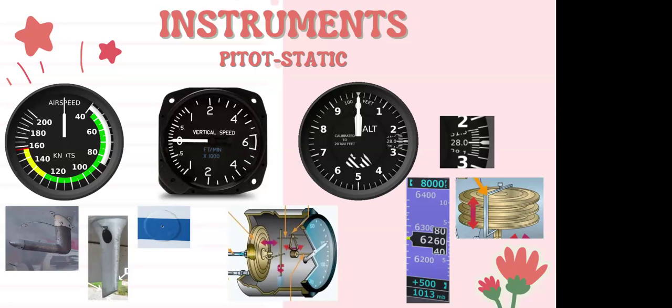Now, there's another line going to the case, but it has something called a calibrated leak or metered flow, whatever makes more sense to you. It's kind of like a toll bridge at the line to the case, where it has to meter it in rather than getting direct flow. The reason for that is to cause a pressure differential.